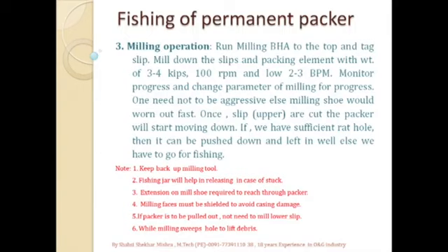The fishing jar will help in releasing in case of stuck up, and here we have to ensure the milling shoe must have an extension above that, such that it can swallow the cut length of the pup joint and the whole packer body till the bottom slips.